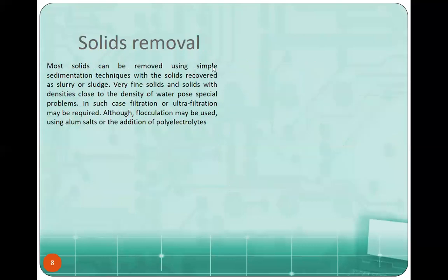Next, solids removal. Most solids can be removed by using sedimentation technique with the solids recovered as slurry or sludge. They just sink, like septic tanks, right? In sedimentation tanks, the solids are left at the bottom while the liquid on top just passes through.